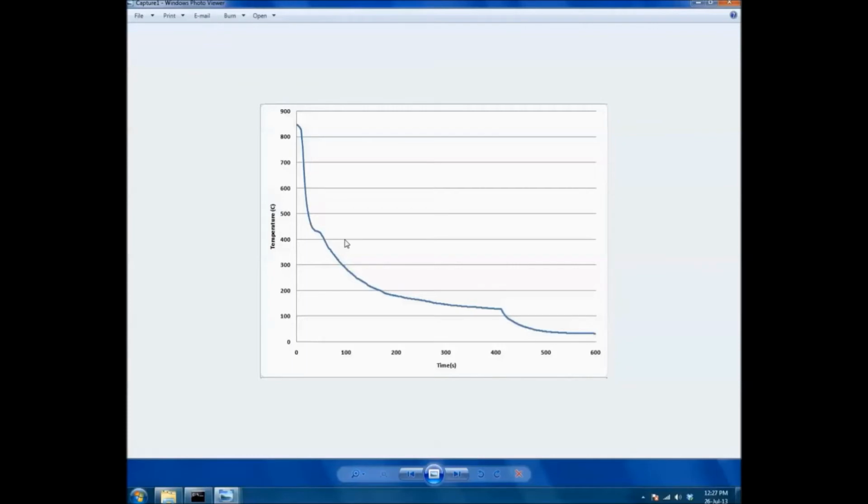Now, such details of the cooling curve will be totally missed if a standard probe made of a material other than the component being quenched is used, and that too in laboratory conditions. Hence, the reference quench probe is developed to overcome all the deficiencies in the present design of the various quench probes.